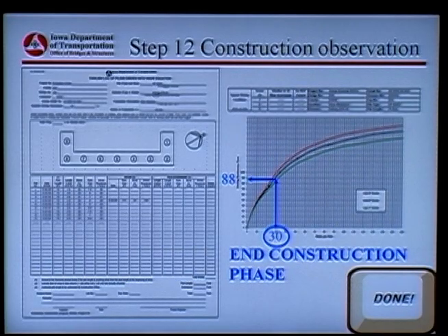And we're done. Now, why were we done? Remember, we had a target capacity in here of 83 tons, right? So at end of drive, remember, we said it was 83 at end of drive, but if we wanted to get the full capacity the structural engineer needs at 7 days after the setup, then we needed the higher capacity, right? And we're relying on the setup to carry us the rest of the way. So since the 88 exceeds the 83, we would accept that pile.